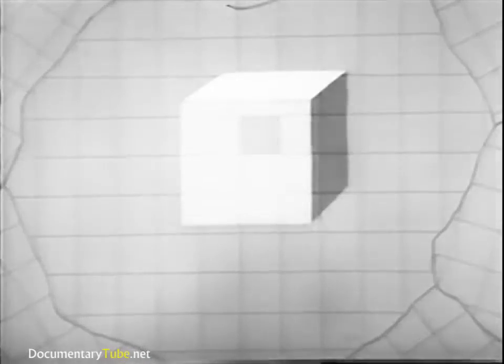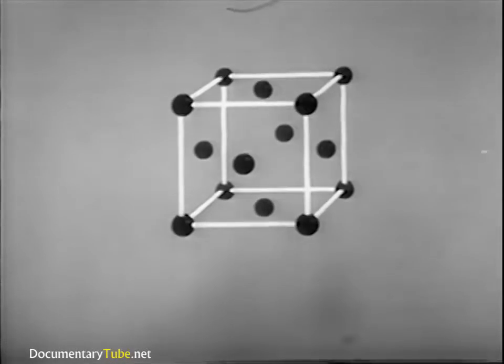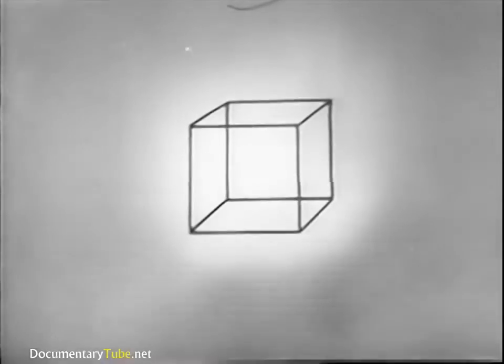Microscopic study of a cross-section of an aluminum alloy specimen reveals a network formed by the boundaries between grains of the metal. Each grain is an accumulation of individual crystals or unit cells. The single crystal or unit cell is conceived to be cube-shaped with atoms of the metal arranged in regular order, one at each corner and one in the center of each face of the cube.